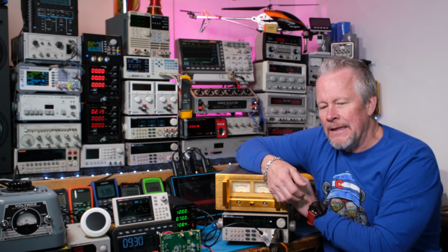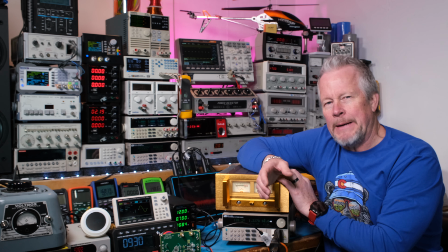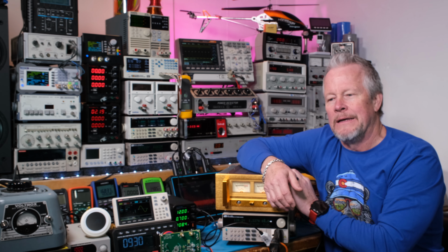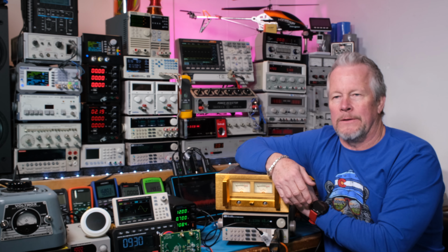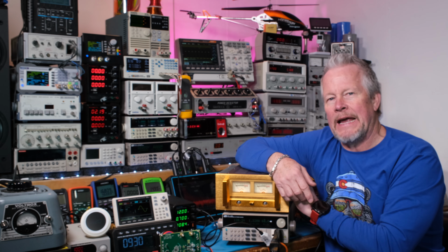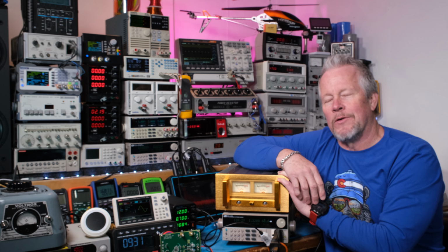So I could go to a much smaller capacitor instead of the big capacitor because I was using the regulated output. And a regulated output is a regulated output. It holds the voltage flat. Yeah, there could be some dips, but the regulation circuit will do everything it can to keep that voltage level, right?